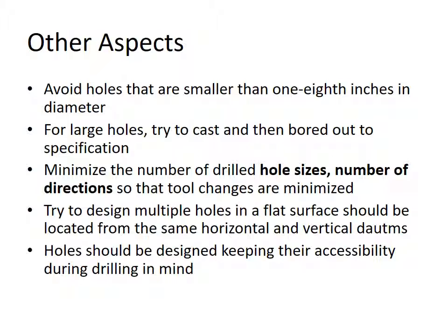Holes with different sizes should be avoided because tool changing time would be counted in manufacturing time, and similarly the number of directions needed to drill holes should be minimized, because rotating and orienting the tool would also increase manufacturing time. When there are multiple holes on a workpiece, it should be preferred that they have equal distance from the bottoms, because then we can use a fixture which could drill multiple holes at a single time.